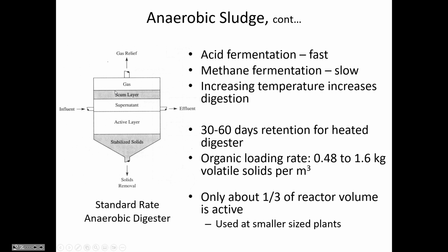And so putting some sort of a flexible lid on these anaerobic digesters so that the gas layer can go up and down. And remember that this is a flammable gas. And so there's a whole other set of considerations that come from that from a safety standpoint, that when you've got a flammable gas and you're pumping things in and out, you have to be pretty careful about electrical leads and lights in the buildings that house these digesters. And so we'll look at some photos that illustrate all of that.